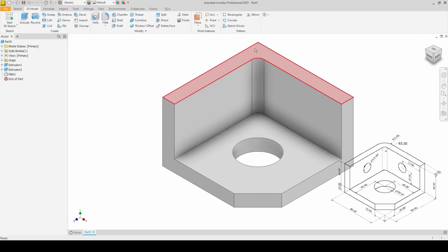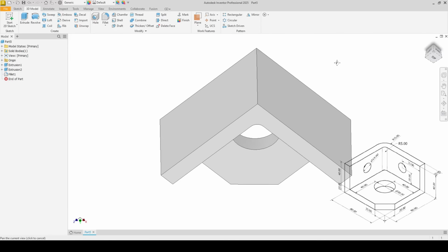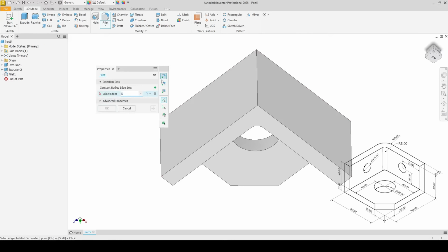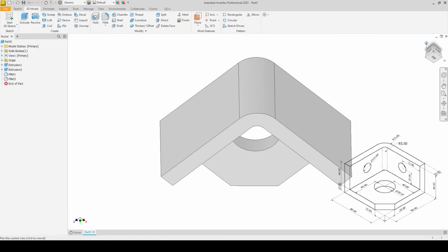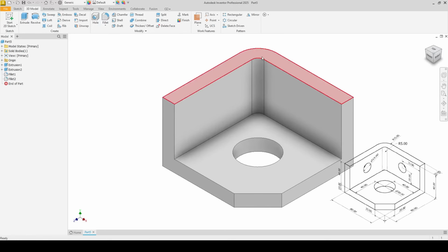It's looking nice. Got a fillet on the back of 15mm. So let's take the view cube, turn this around, choose the fillet tool again, go to our input 15mm, select this edge there, press OK. Let's click on the home button. And there we have our 2 fillets and our 2 sidewalls. That's looking good.